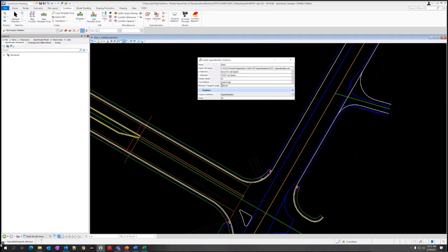And make sure everything else is right, because you still have a chance to set your feature definition. So when I accept this, I think it's going to just go to the next step, and this is going to go away. So just double check it and then accept. Okay, so it does ask me for the minimum tangent length. So I've got one more option. And then it may seem like it freezes up here.